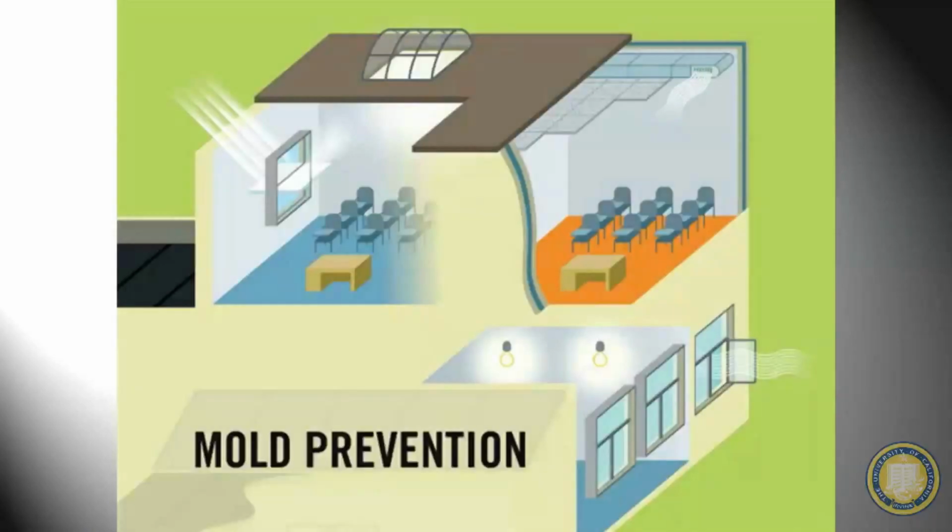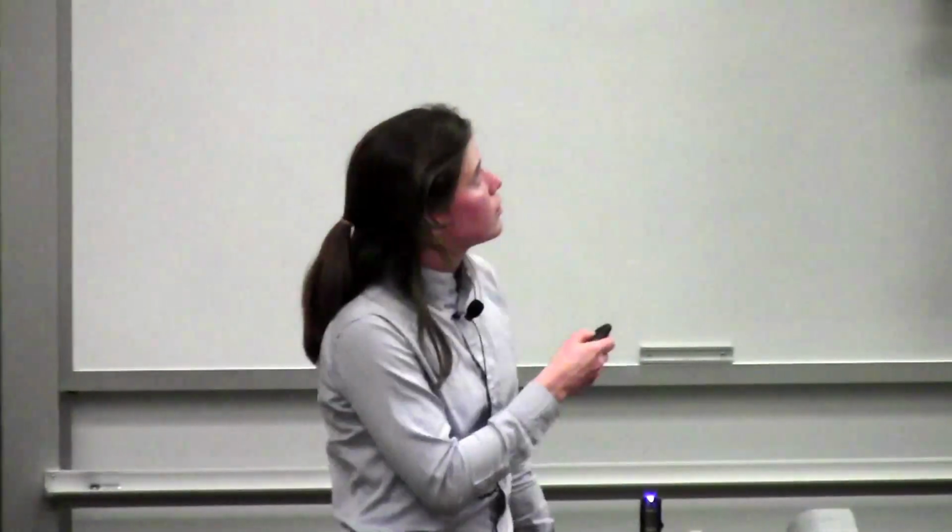Mold prevention is a big issue, and this is part also of green building, one of the social parts of that triple bottom line that we were talking about. So if you have more ventilation, as opposed to sick building syndrome, it can relieve humidity to below 60% with adequate ventilation, and inhibits mold growth. And of course, mold growth can have serious health concerns.